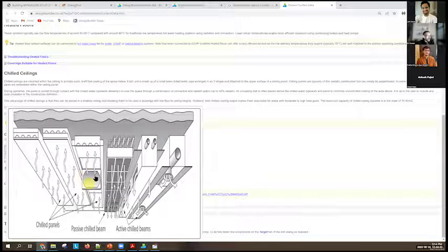Yeah, really what you're looking for is passive chilled beams at that point. So passive chilled beams basically just circulate chilled water through panels at the ceiling, and that's what you call radiant cooling in India. So that's available as well. There's active chilled beams, there's passive chilled beams, there's underfloor air conditioning, there's VAV systems. Many of those are available, but essentially you need to know how to design them. Once you design them, you can model them in DesignBuilder.